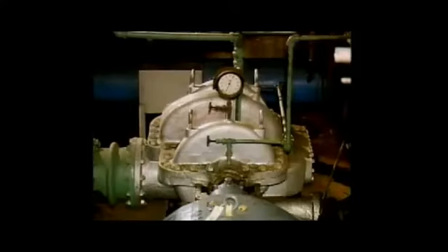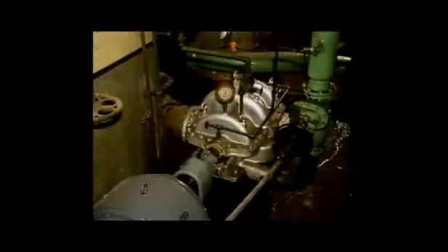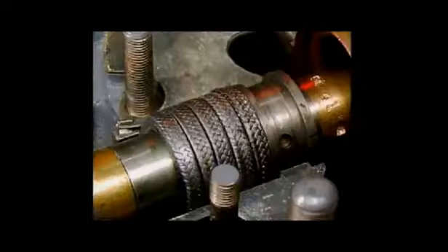On most pumps, a shaft is used to transfer power from a driver to the component in the pump that moves the liquid. The point at which this shaft enters the pump's casing must be sealed to keep the processed liquid inside the pump. The area between the shaft and the casing is commonly sealed using either packing or a mechanical seal. The simplest way to seal between the shaft and the casing is to use packing.